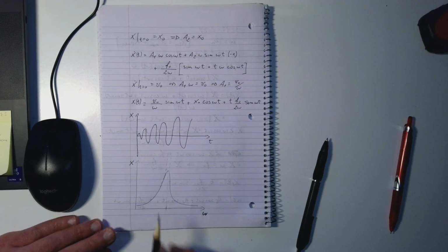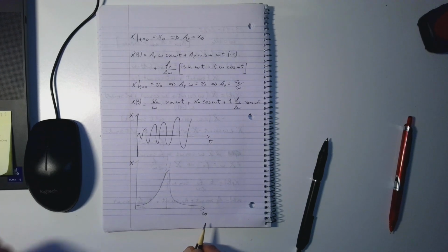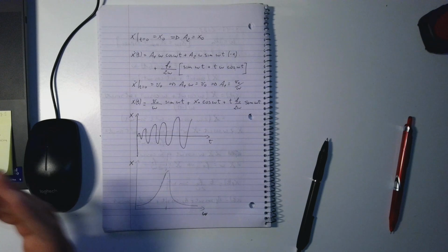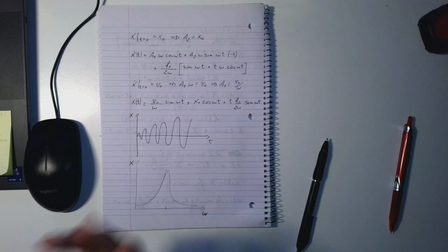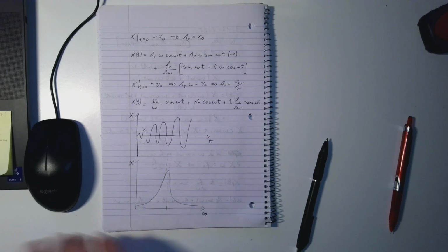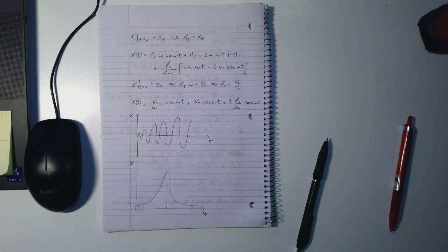So every time we get closer to the natural frequency of the system, it is a dangerous situation, because we can have a sudden increase of the amplitude of oscillation, and if we have too much displacement, we can have too much deformation, which means plastic deformation and eventually rupture of the whole structure. So when we design our structure, we always want to be very far away from the natural frequency of the structure. Makes sense?